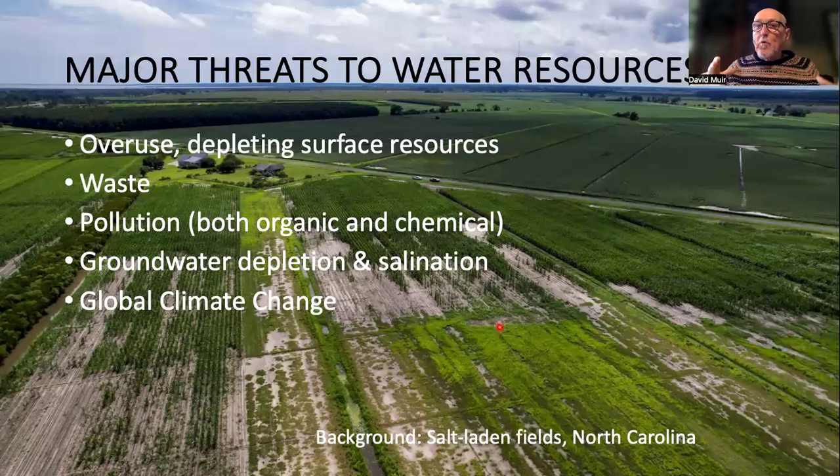The groundwater lies very deep, but it acts as a support, as a foundation for the sediments above it. Abstract the groundwater too much, abstract it faster than it can be replaced, and the ground will begin to sink. But the second and really important problem for agriculture is that these very deep groundwater stores, the aquifers, very often have underneath them a layer of salt water, which has come in from the sea. It can go very, very far inland in these deep sediment layers. And if we take out the groundwater, it begins to be replaced by salt water.